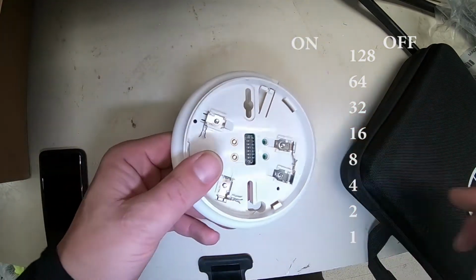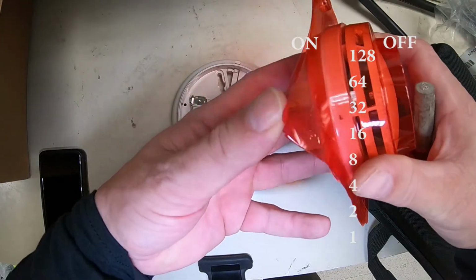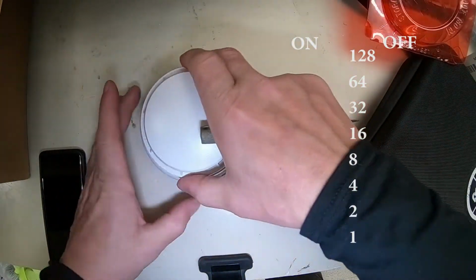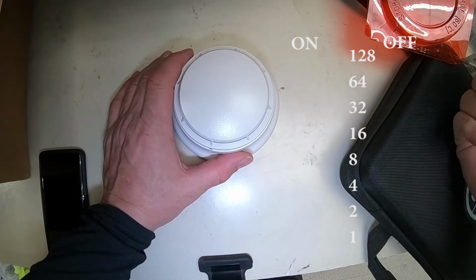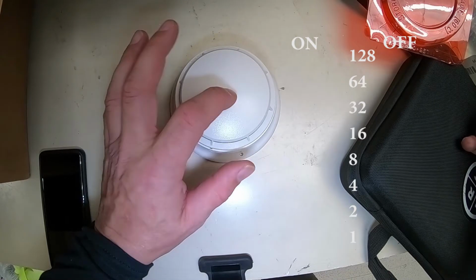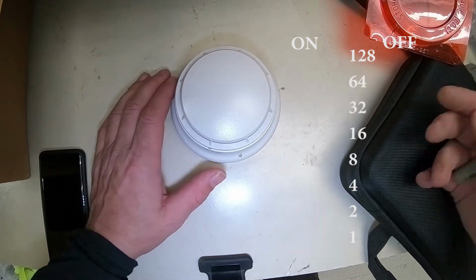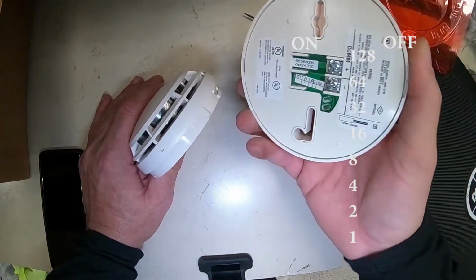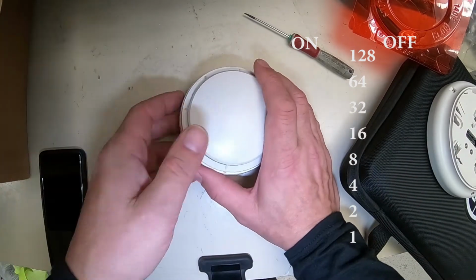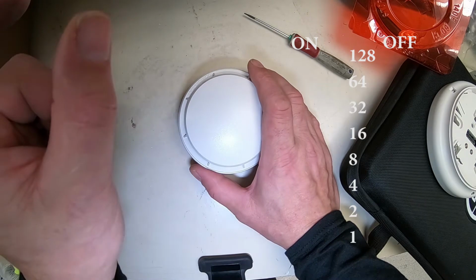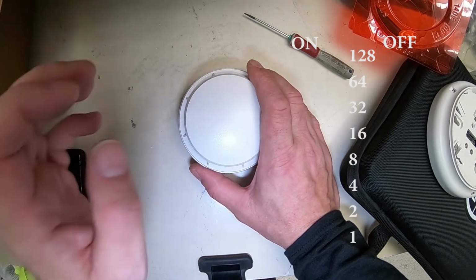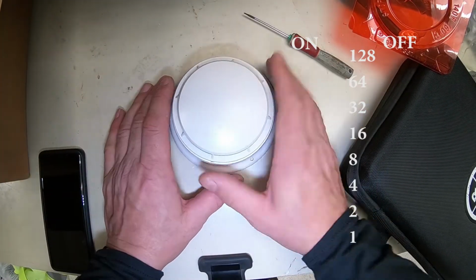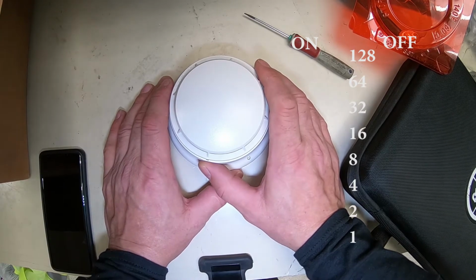Now, if we install this device with a new head, boom, you put this in, it would take about maybe a minute for the panel to realize it, and the LED will start blinking if you did everything right. But since our problem is actually with a duct detector, we're just going to replace the head, which means we didn't have to address the base. The base in the duct detector is actually on a little computer board, but the dip switches are exactly the same. So you set them exactly the same way on a duct detector as you do on a smoke or heat detector head. That's it. Nothing to it. Easy. Hope you gained something from this video.